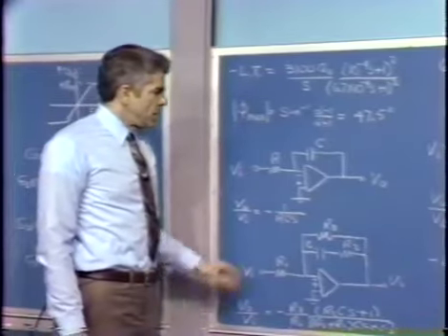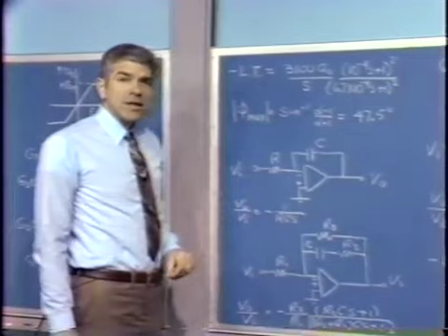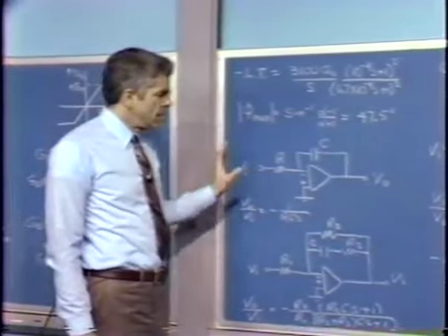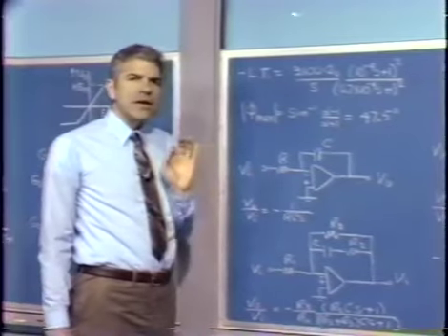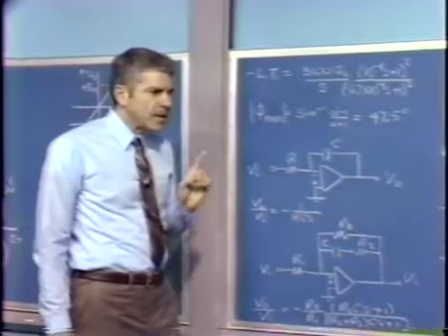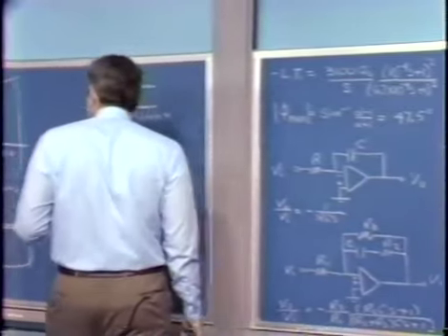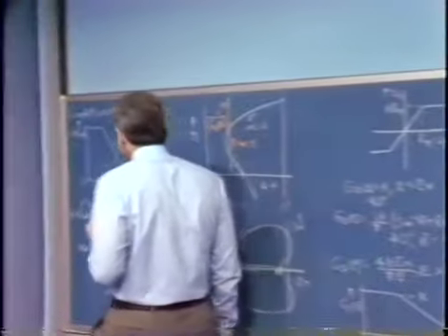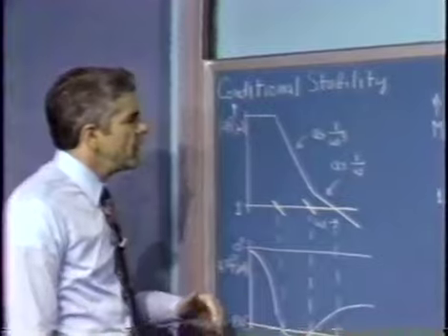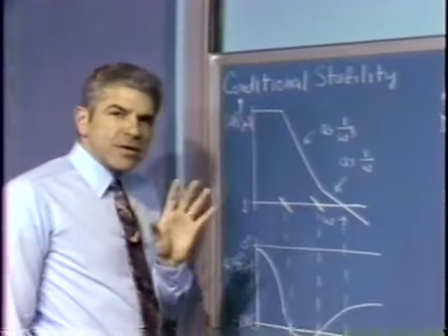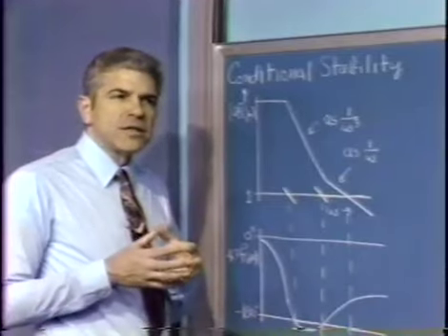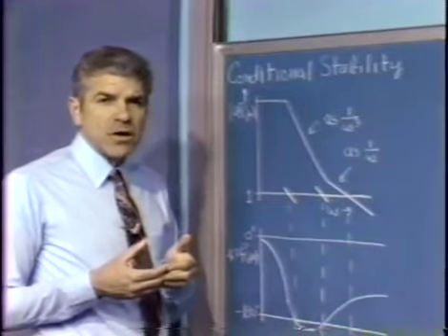In order to implement a system like this, we've simply built it up out of operational amplifiers, but it's not a completely made-up system. The reason that you get into this problem typically is as follows. Let's look back at our original frequency or magnitude versus frequency curve. When we look at a typical feedback system, there's usually some process that limits the maximum achievable crossover frequency.